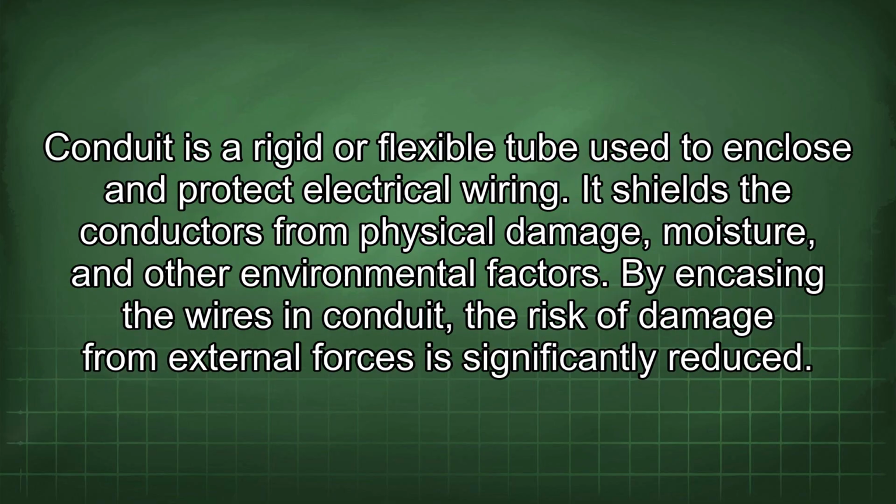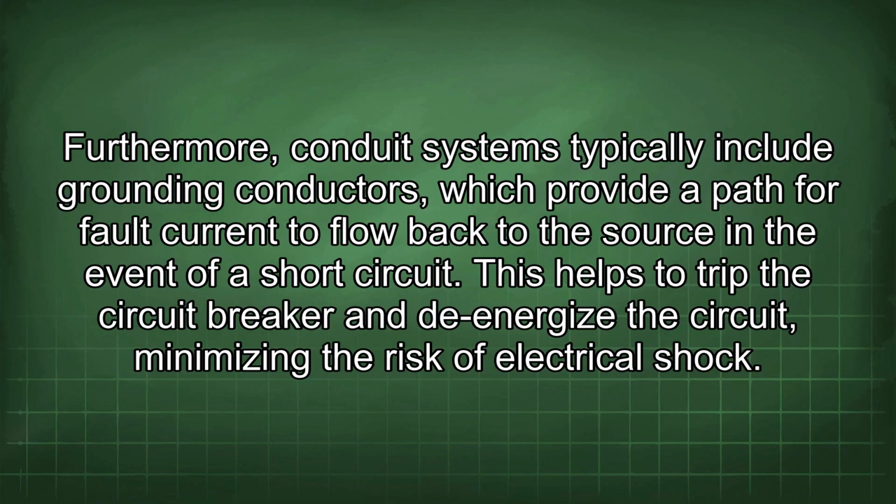Conduit is a rigid or flexible tube used to enclose and protect electrical wiring. It shields the conductors from physical damage, moisture, and other environmental factors. By encasing the wires in conduit, the risk of damage from external forces is significantly reduced. Furthermore, conduit systems typically include grounding conductors, which provide a path for fault current to flow back to the source in the event of a short circuit. This helps to trip the circuit breaker and de-energize the circuit, minimizing the risk of electrical shock.